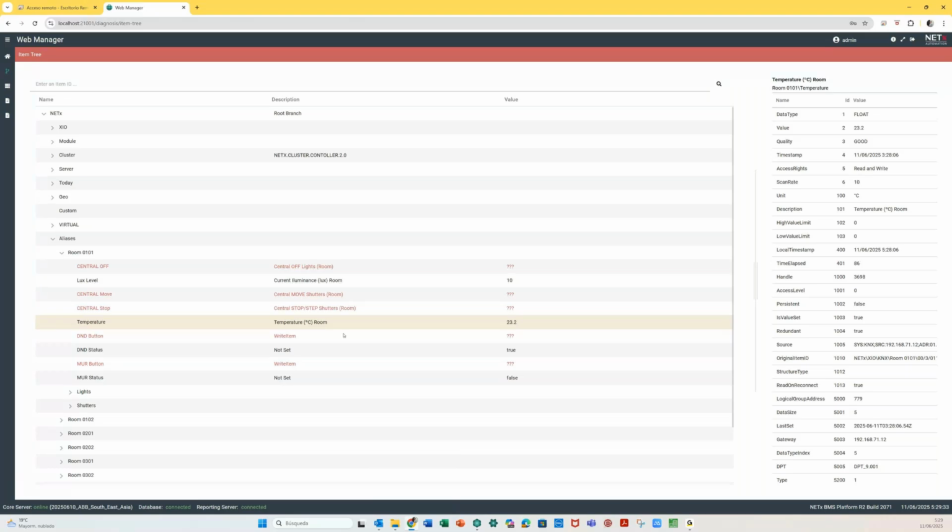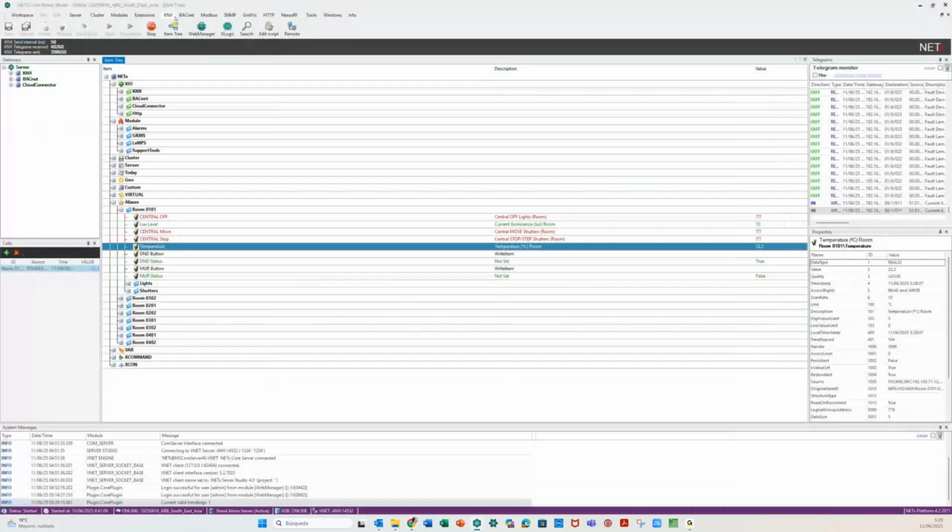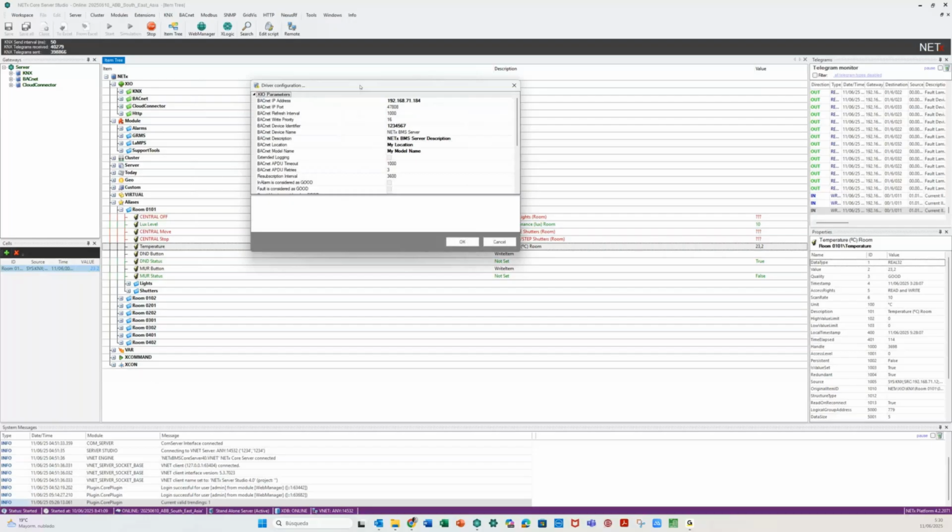because the URL will be, instead of localhost, just the IP of my server. So it's very simple to identify which is the IP of my server. I can do it with command window from my computer, but also here with a BACnet driver configuration, because you may remember when we did the scanning, it prompted a message, localhost is not valid. You have to select the IP of the device that will scan the network.